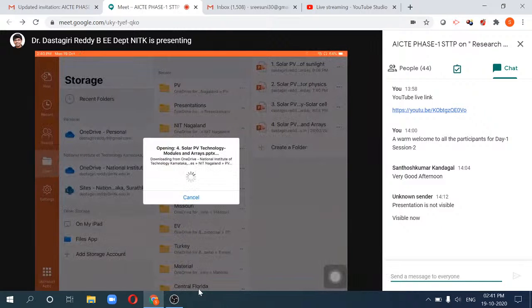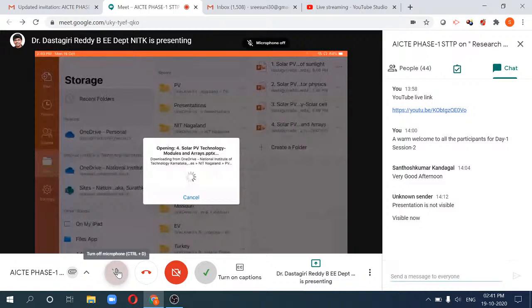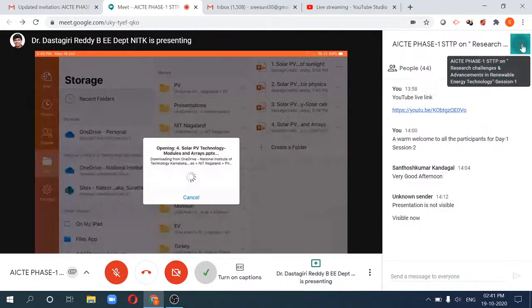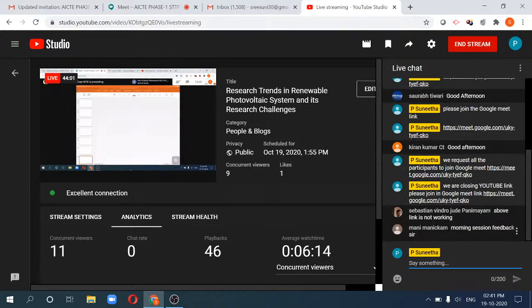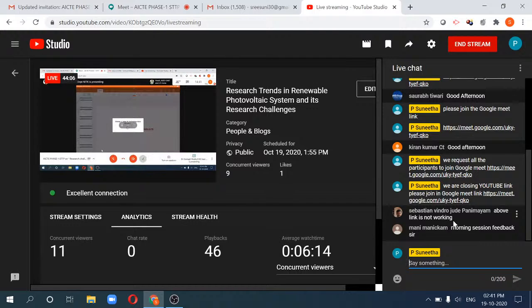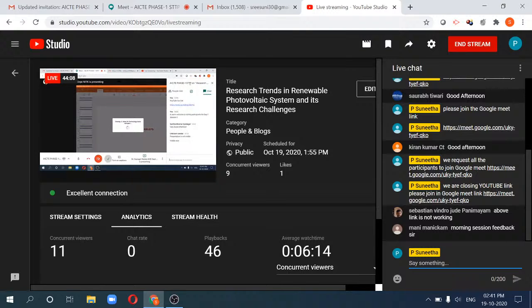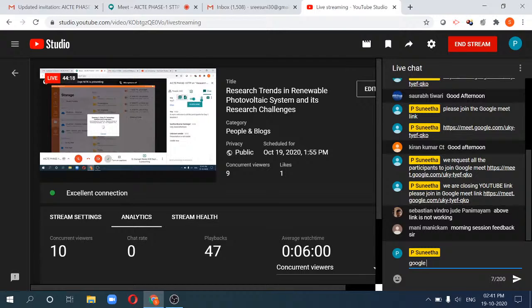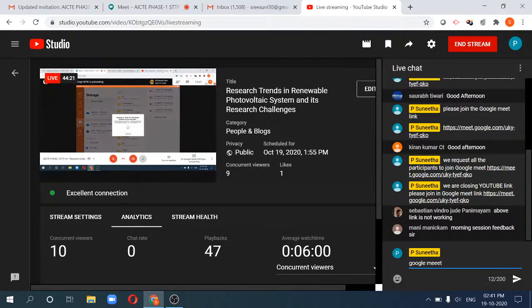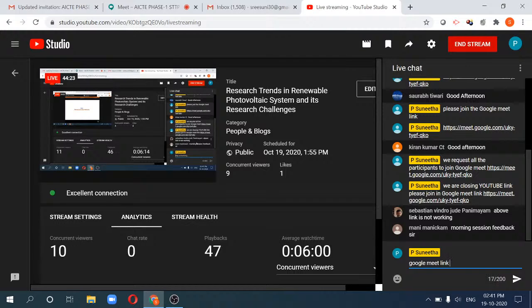Basically, a solar cell works with four steps: generation of light-generated carriers, that is holes and electrons. Second, you have to collect them, by utilizing the electric field available inside the PN junction. Because of this separation, a voltage comes into picture. Then when you connect any load across the junction, the current will pass through outside the junction. So we are talking about the current which is not flowing through the junction, but outside it.